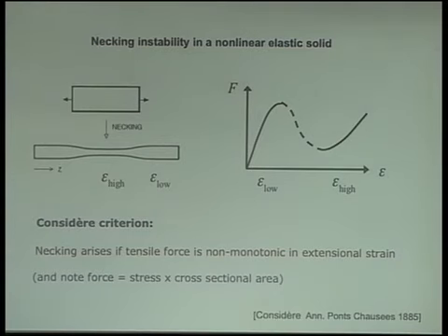So in a way, this looks, to someone from the shear banding community, a little bit like shear banding, but it's actually an extensional band. So it's a region of high strain and a region of low strain that can coexist with each other. And just for use later, obvious, but just to point out that force is stress times cross-sectional area. Okay, so that's something that's been talked about in the solids community actually for, as I say, over 100 years or so now.